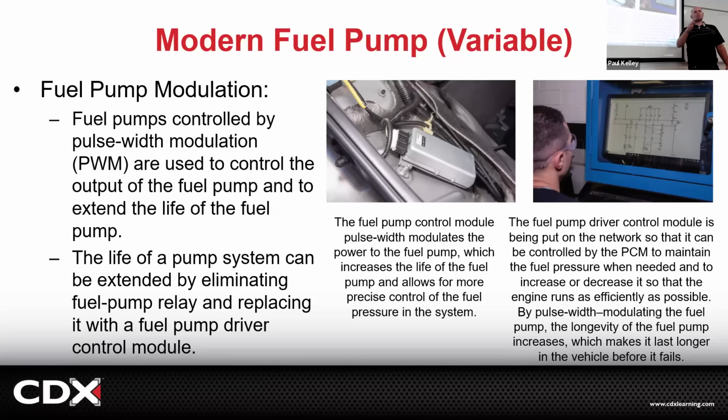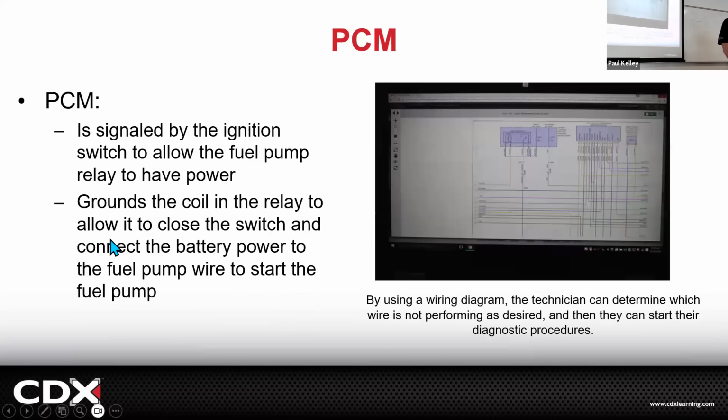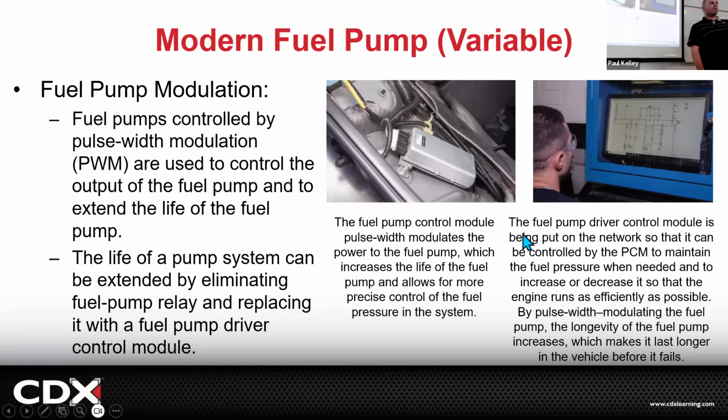But what about for the technician? You used to go back there on the old system with a test light. Does the test light light up at the fuel pump? Yes. Does the fuel pump work? No, fuel pump's bad. You could do that with a meter, a little more modern. Does it have 12 volts and ground? Yes. Does it work? No, fuel pump.